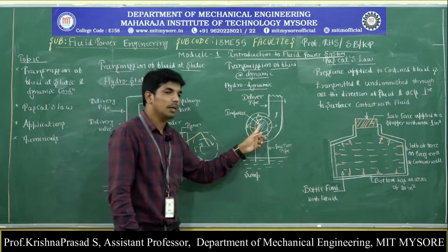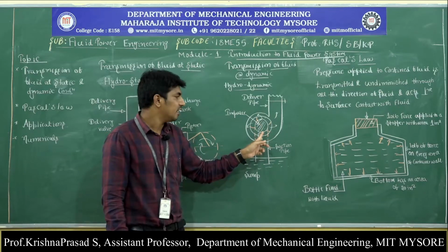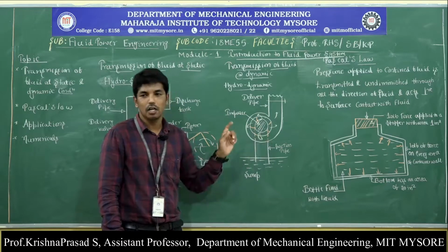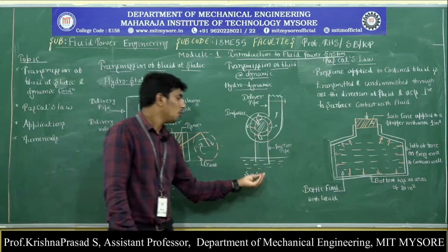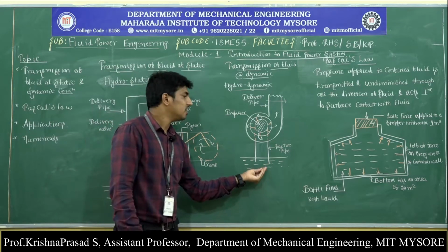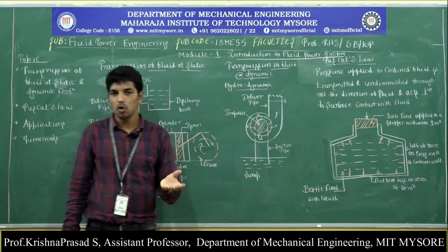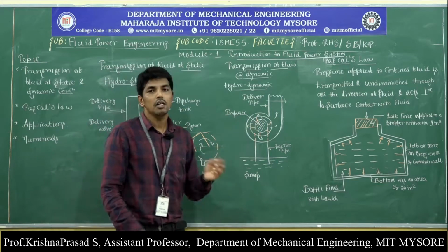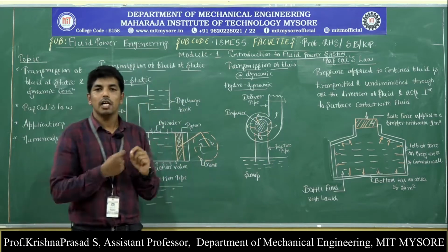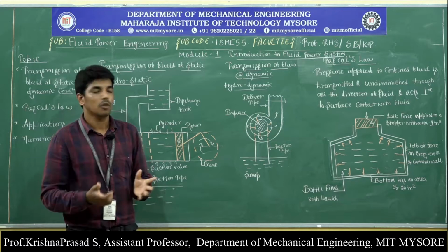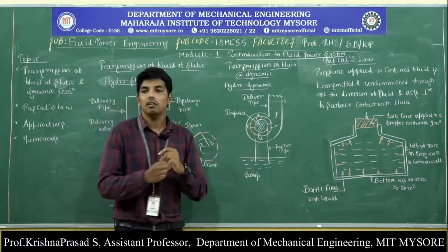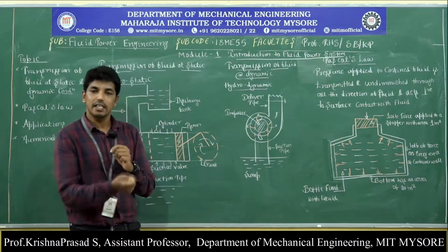Due to the rotation of the impeller, a suction is created inside the impeller. Due to the suction, the water from the sump enters into the center of the impeller. Once it enters into the impeller, due to the rotation of the impeller, centrifugal force is going to develop. Due to the centrifugal force, the velocity of the water increases.